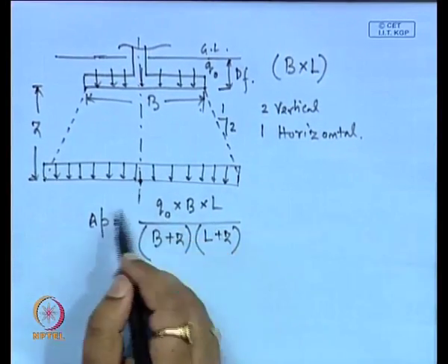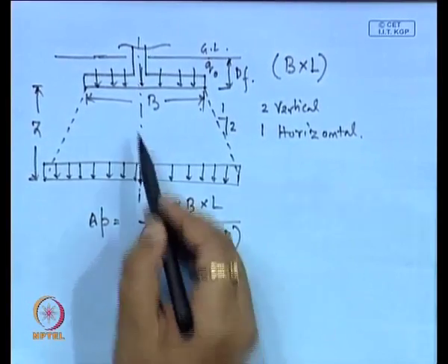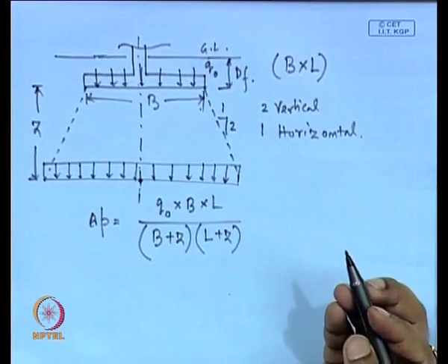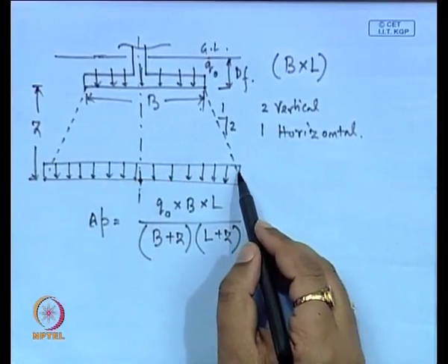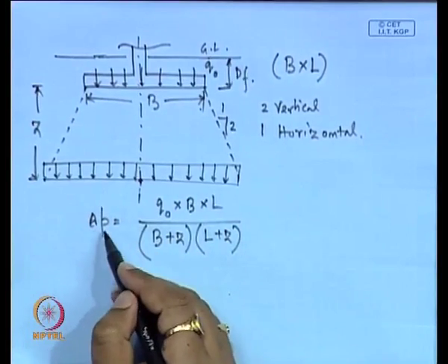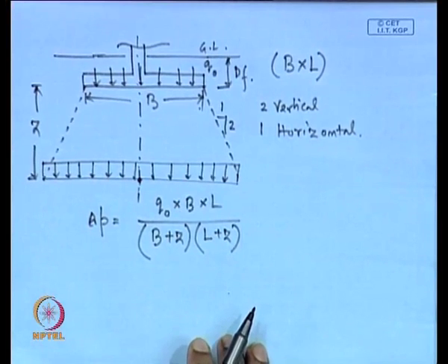In this way we can determine the increment of stress due to this footing. Either you can use the Boussinesq procedure or this approximate method, which is one approximate method to calculate the increment of stress at any point below the foundation base.